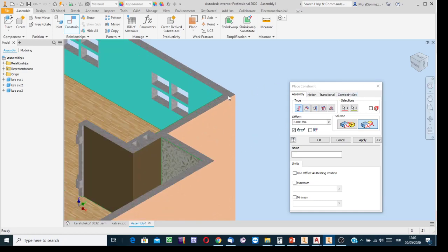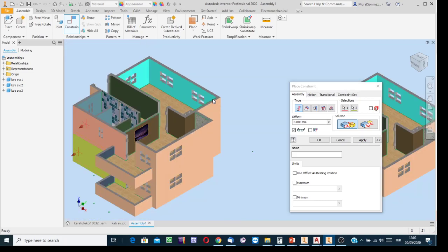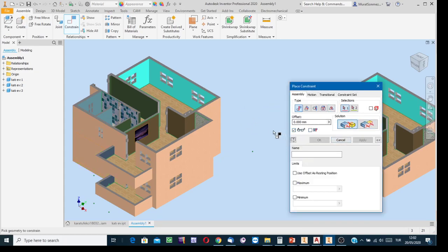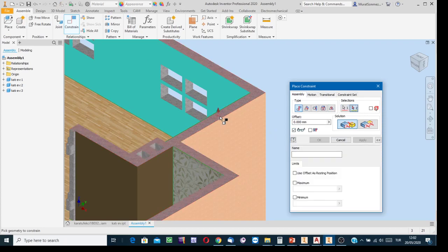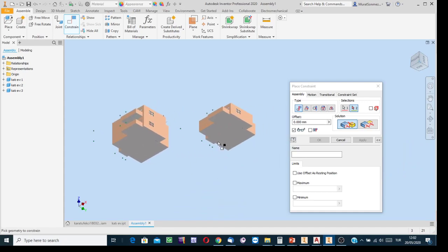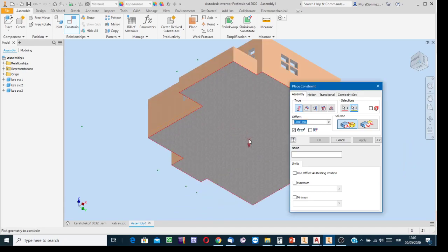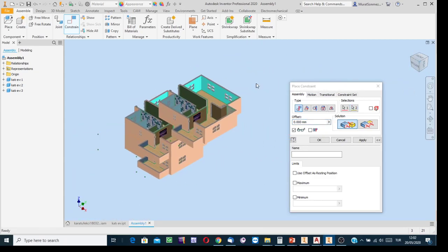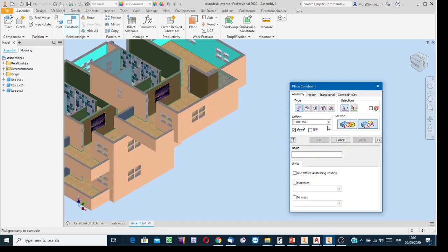Continue for the third. Select the face-to-face contact option, and indicate the surface with the face-to-face solution. Indicate the bottom side surface of the model of the other flat, and say that these are to be in contact. Click on the apply button, and then similarly select the parallel positioning option.